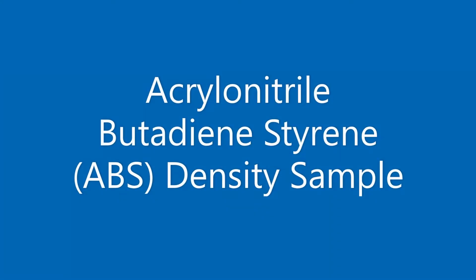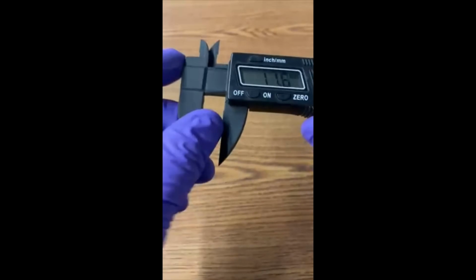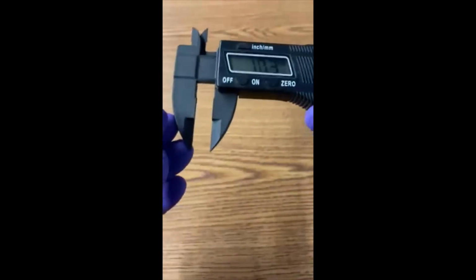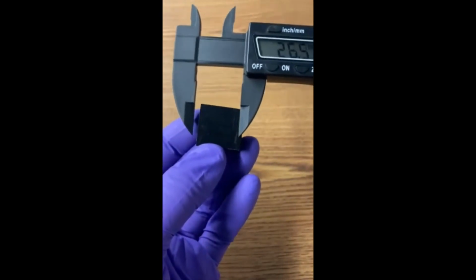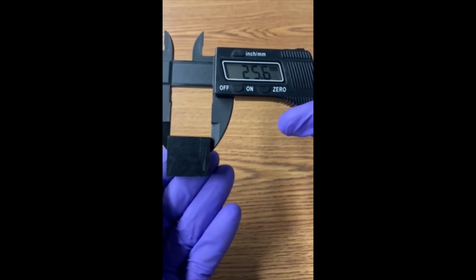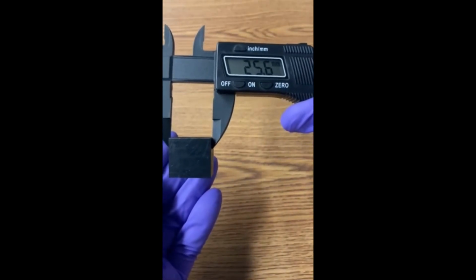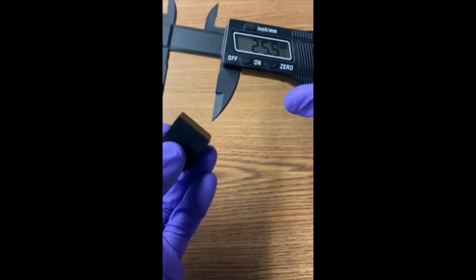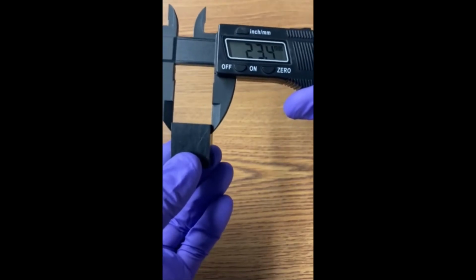Now we outline the method to determine the density of each material. We will take each material and measure the dimensions of the rectangular prisms machined from each of the polymer materials to determine the volume of each sample. We're going to measure the length, width, and thickness of each rectangular prism. We'll measure them at two different ends and take the average value and use these three measurements, meaning 6 measurements in total, 2 for each side of the sample. We will average the 2 measurements from each side of the sample and use those to calculate the volume of the sample.